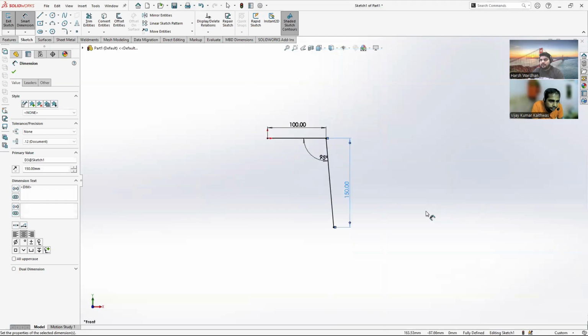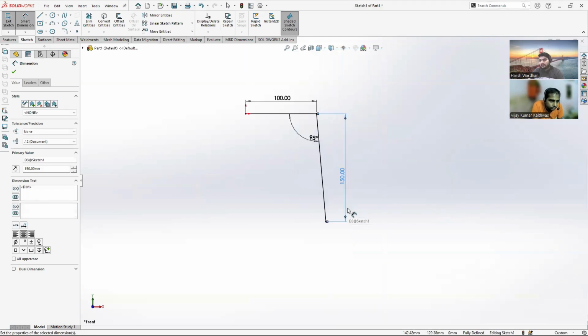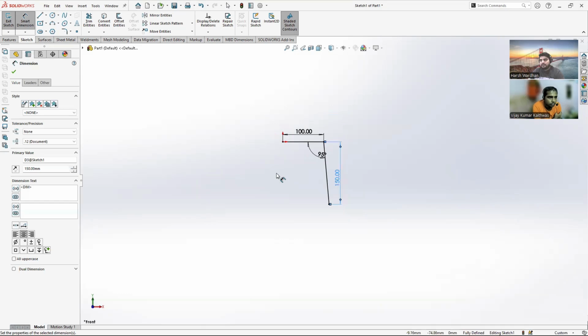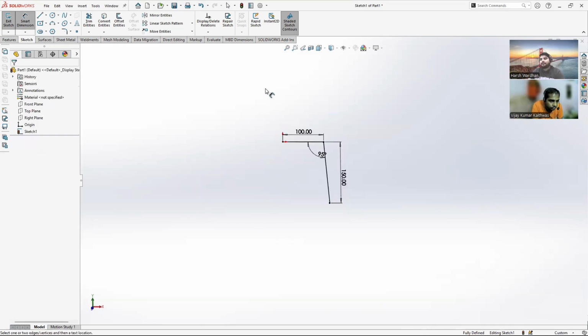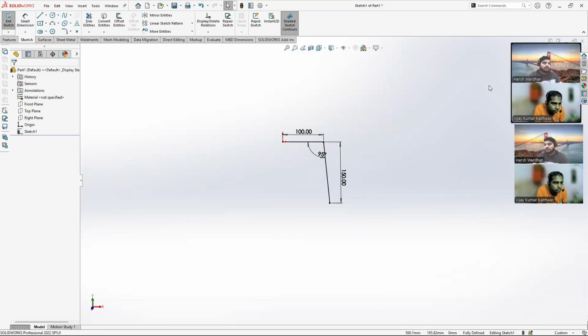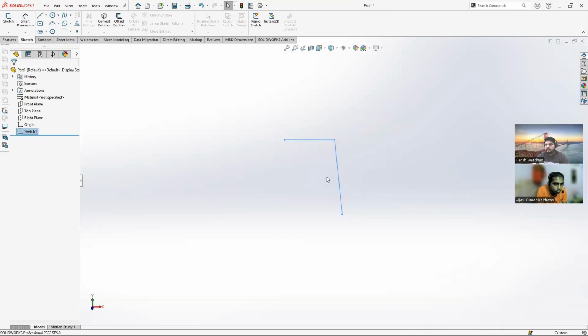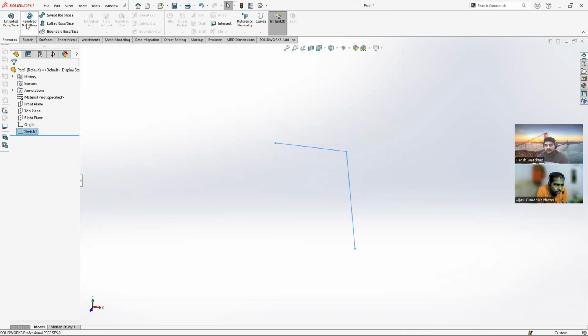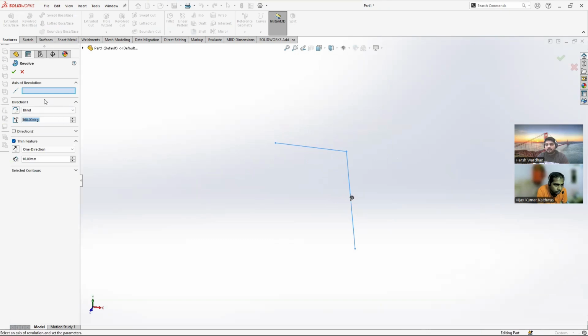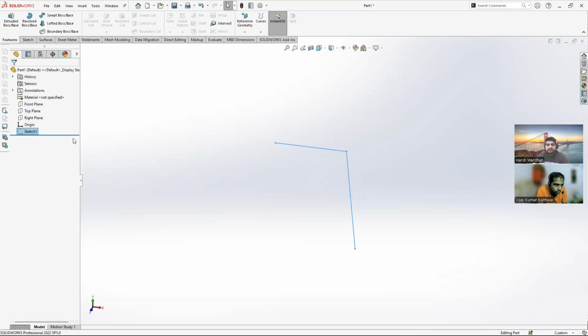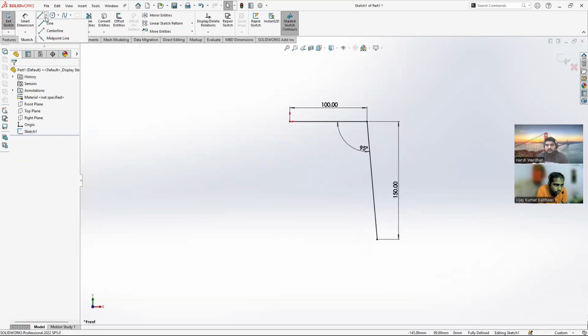Yeah, right. It's a lamp, so it has got a big bulb inside it. Now, select and close. Now, we revolve it. Feature, revolve. Okay. What we missed is we didn't do the axis. So we go to it again and then we create an axis.